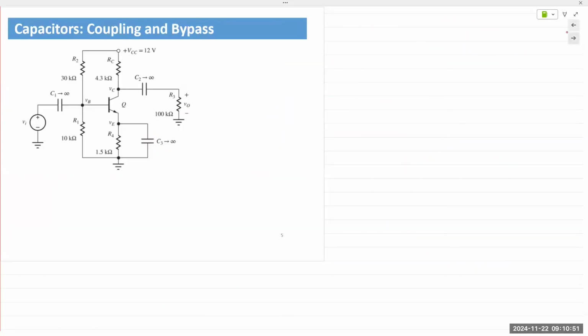So we performed the load line analysis for the common emitter amplifier, right? Where we are applying a DC biasing voltage, then we apply a small AC input signal and obtain the amplified output. Now, when we analyze these circuits, we apply the superposition principle. And the great thing about this is we can treat the DC and the AC sources separately, so we can analyze the circuit separately.